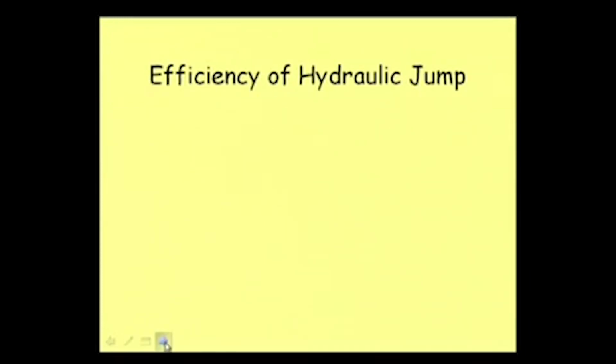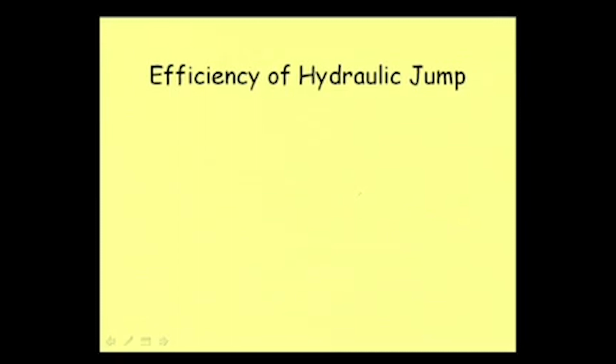Well, then what is the efficiency of a hydraulic jump? As a hydraulic jump is being formed in many cases for dissipating energy, let us see how we view the efficiency of that particular device. Well, if E2 is the energy after the hydraulic jump, that is here, say y2, and this energy level here is E2 and the energy level here is E1.